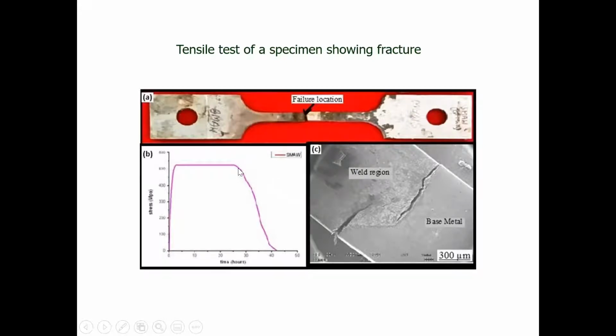So you need to understand, as you start to stretch the material, as it becomes more ductile, if you like, and we've started to form the crack, then the stress actually goes down until we reach the point where we have failure and it breaks and there is no stress anymore. It's gone down to zero. And this particular case has taken 40 hours to get to that point.